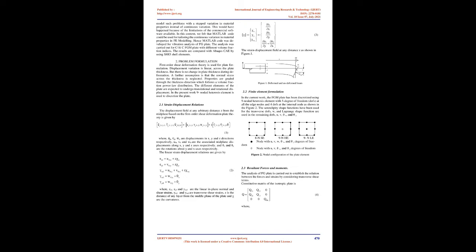Jyoti Vimal et al. [5] have studied the free vibration analysis of functionally graded skew plates using the finite element method. The first-order shear deformation plate theory is used to consider the transverse shear effect and rotary inertia. The properties of functionally graded skew plates are assumed to vary through the thickness according to a power law. It is found that when the length-to-thickness ratio of functionally graded skew plates increases beyond 25, the variation in the frequency parameter is very negligible, and also found that a volume fraction exponent that ranges between 0 and 5 has a significant influence on the frequency.